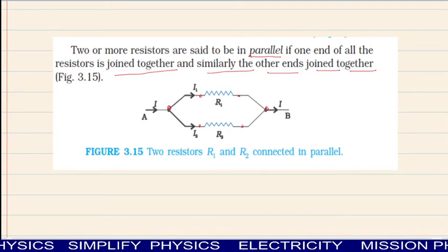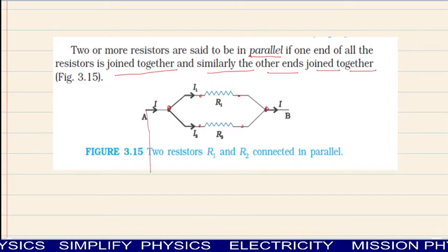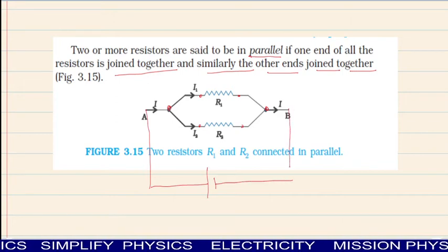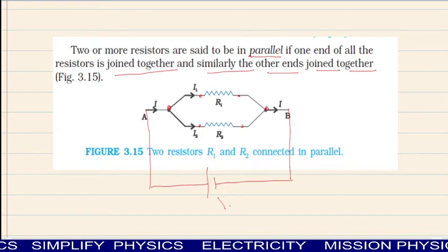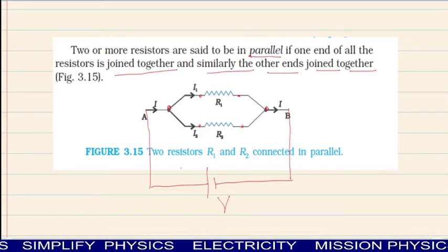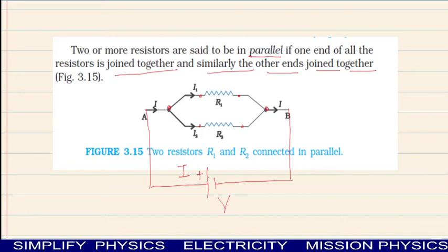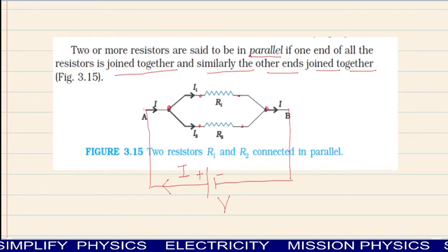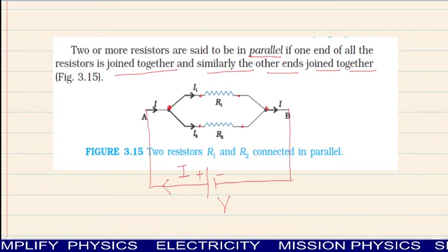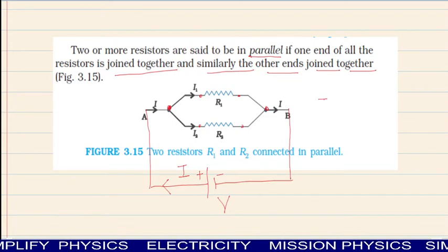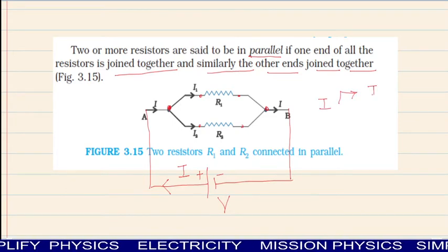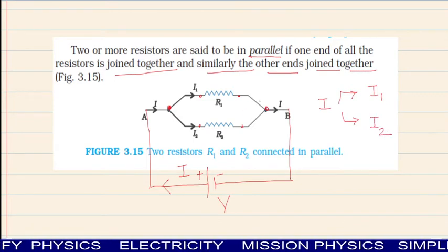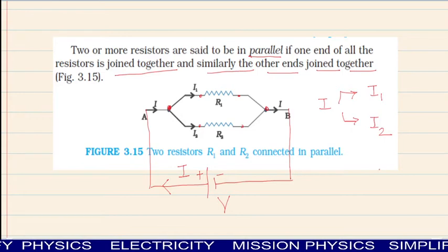अब इस कॉम्बिनेशन के साथ हम एक EMF सोर्स कनेक्ट कर देंगे in this way। So EMF source of V will be creating a current extracting from the positive terminal of the cell। सो जैसे ही ये करंट ए पॉइंट से फ्लो होकर इस जंक्शन पर पहुंचेगी, this current I will be divided into two parts I1 and I2. अब डिपेंड करेगा कौन सा रेजिस्टेंस कम है.